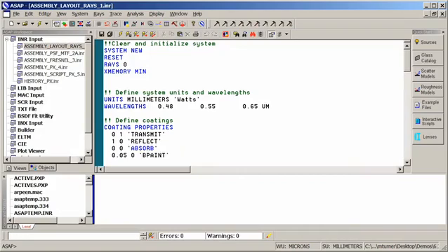In this particular case, what I've done is designed an optical system, in particular a Cooke triplet, using a lens design program, although I could have also done the design and optimization within ASAP. I've exported that file from my lens design program and using one of the available translators have imported that into ASAP. So I now have the full lens structure within ASAP. I can then take that information from ASAP and export it as an IGES file, which I can then bring into a CAD program. The reason for doing this is so I can develop, or have my mechanical engineer develop, the mechanical structures necessary to mount this optical system. And let's take a look at doing that.